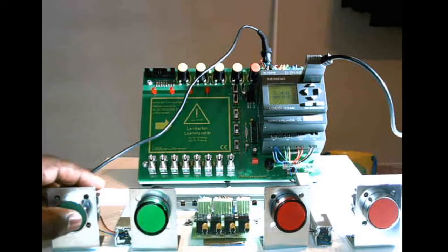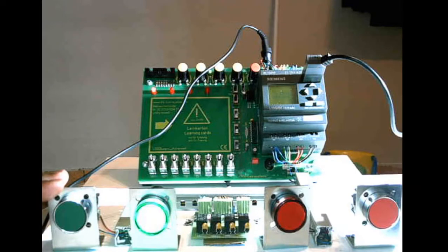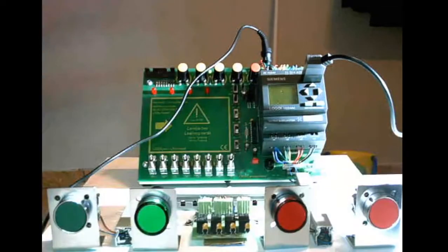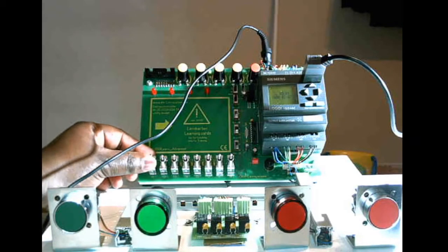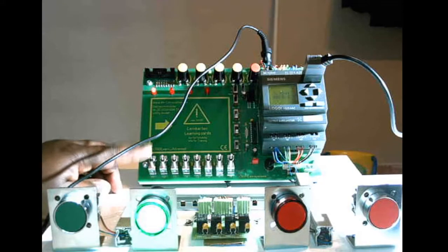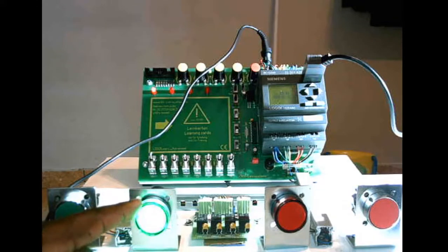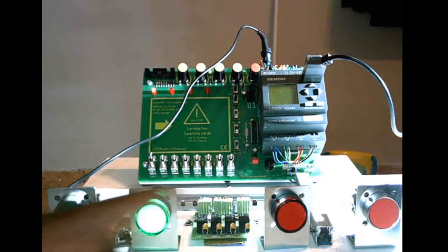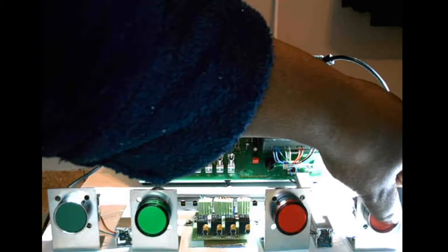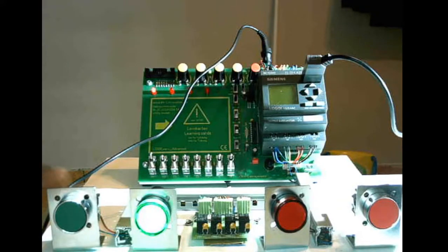So now when I press I1, the LED goes on and it retains, and when I press I2, the LED goes off. The reason why we are using push buttons instead of the switch is that if you start the process with the switch, here's a switch here, I'm going to press the switch and I leave it in the on state and the LED remains on. So now let's check what happens when we reset the process. I reset the process. You can see the LED is off, but when I let go, the LED is on because of the I1. That's why we don't use the switches, but we use the push buttons whenever we wire our machines and when we program our machines.